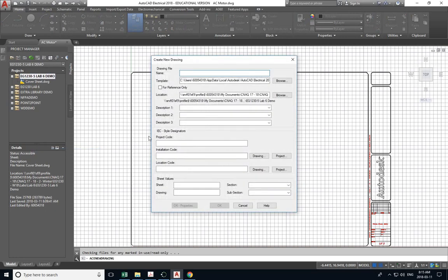Add, it's like we added the cover sheet. It's already there in the folder. You just tell the project that this is part of the project, so that the file where the project settings are already recognizes it as part of it. You'll see later on when we do the bill of materials, actually scanning all the project files. Or when we do wire numbers, you have a group of drawings. You can tell AutoCAD to do the wire numbers for all the drawings in the project.